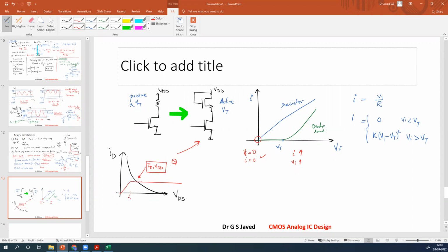And this will be where Vt will happen if you want. And this is the point where VDD minus Vt is. So beyond VDD minus Vt, current is 0. So this will be the condition, assuming Vd is here. Now the transfer function of the CS amplifier will still stay the same. What is it? The transfer function of the CS amplifier is expected to be like this. Sorry, it doesn't go to 0.